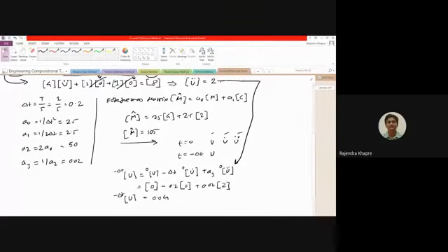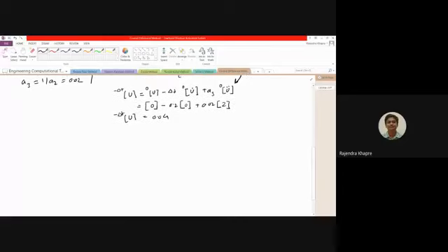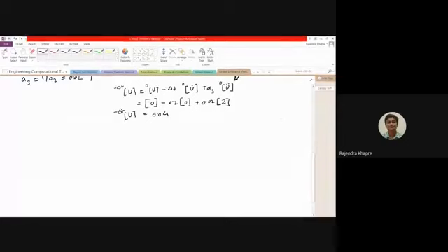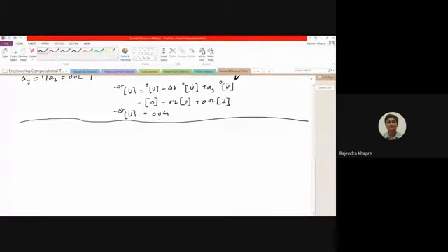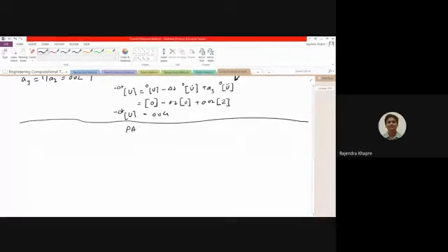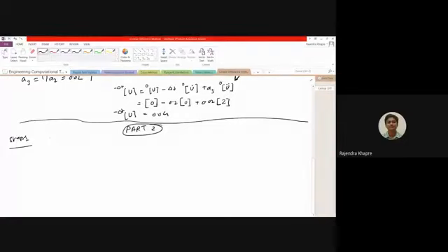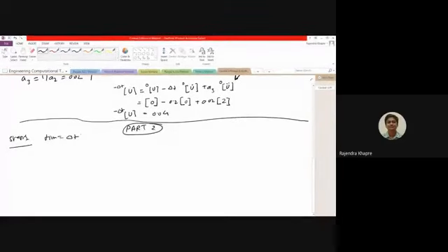So this completes part 1. In part 1 we have calculated all the integration constants, the effective mass matrix, and the displacement at t is equal to minus delta t. Now we are going for part 2. I am writing down over here part 2. Now in part 2 I am going for step 1. In step 1 I am going to calculate the displacement, velocity and acceleration at time t is equal to delta t.